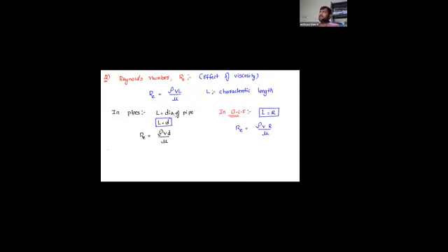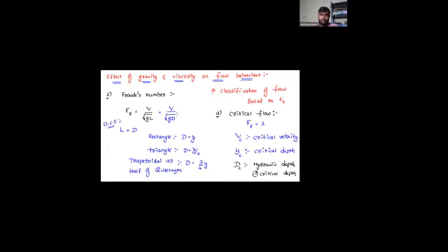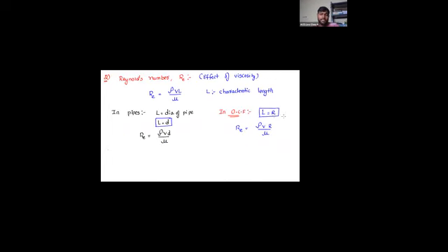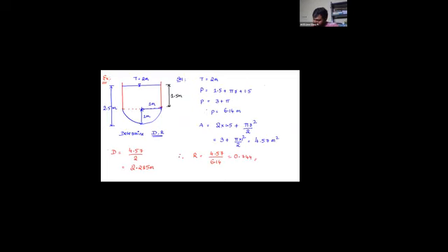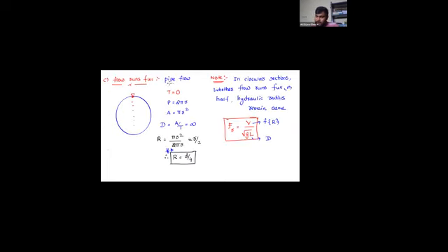So some of the people were asking me, what is the significance of hydraulic radius and hydraulic depth? Sir, hydraulic depth is used in the Froude number to classify the flow. In the case of the Froude number, L is equal to D. And in the case of the Reynolds number, L is equal to R. Sir, now you know that in pipes, just go back. When the flow runs, this is the pipe flow or not. What is the R value? D by 4.